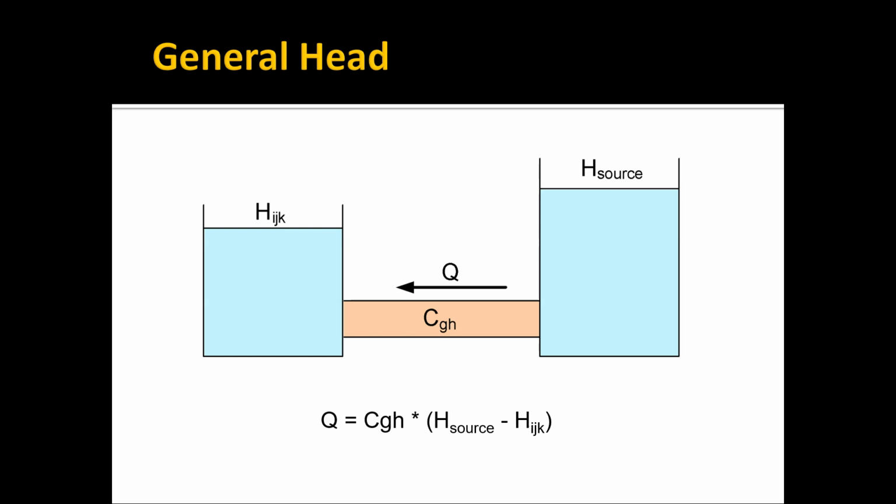This is looking at an individual cell. And the greater the head difference, the greater the flow rate. And if the water table, the head in the cell, is greater than the stage in the lake, there's water going from the aquifer to the lake, and that sometimes happens. And some mountain lakes, for example, are fed to a certain degree by groundwater. And so this can go in either direction, and using this equation we'll get the proper sign.